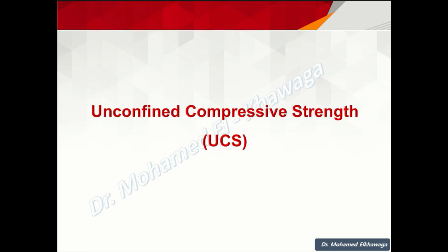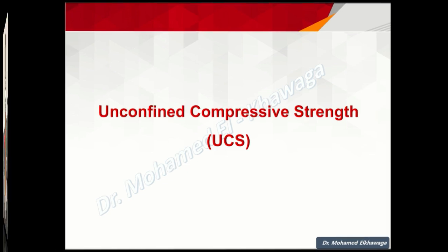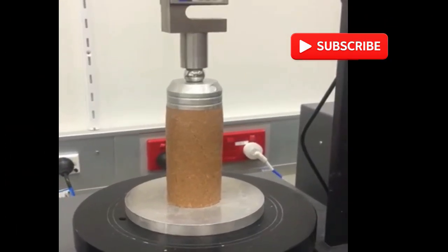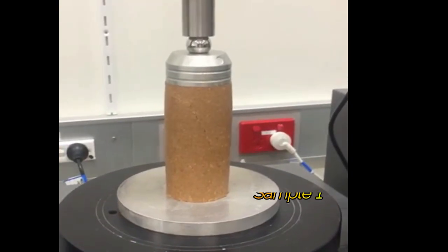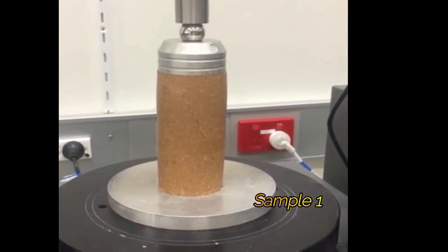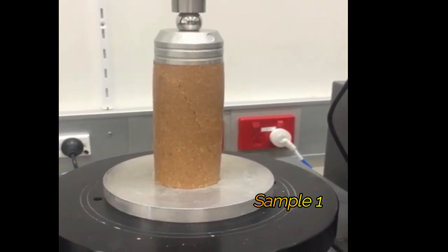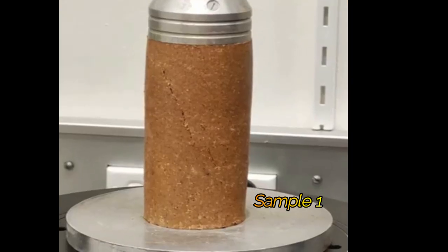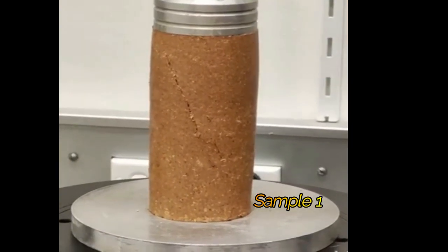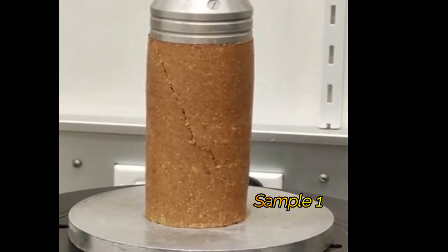Let's get started. As the applied load gradually increases, carefully observe the rock specimen. Eventually, shear failure occurs. Notice that the failure plane is inclined, indicating that the rock failed in shear. This inclined failure plane is a key feature of the UCS test and helps us understand the rock's failure mechanism.